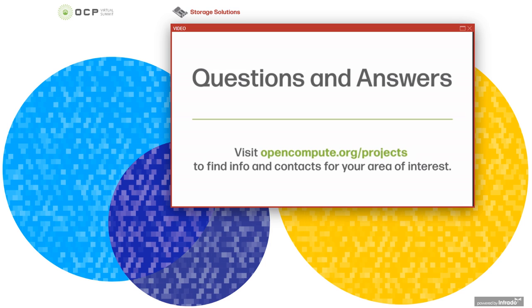There's a question about any details on CXL in the space. Yes, I think this would be an absolutely great form factor for CXL, and I think that there are some very smart people that are looking at doing persistent memory on CXL in the EDSFF form factor. And I think the CXL industry consortium is going to address recommendations for form factors in the future. But as many of you know, CXL runs on top of PCIe 5.0 electricals. So, yes, this would be a fantastic form factor for the CXL interface as well as PCIe and NVMe SSDs.